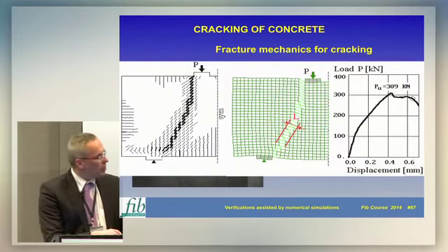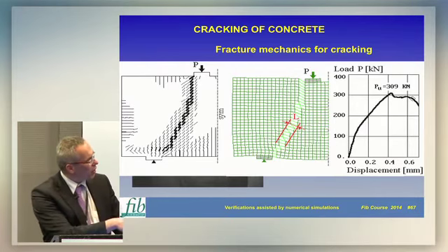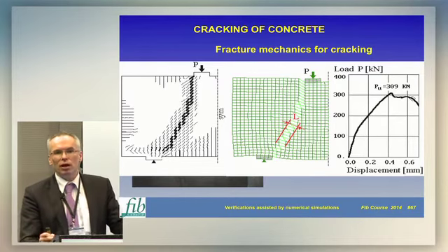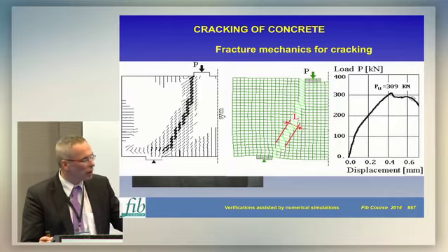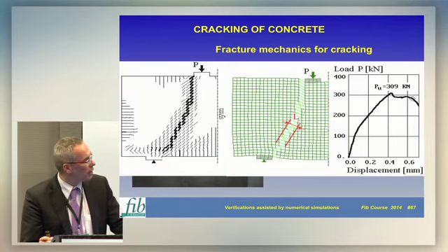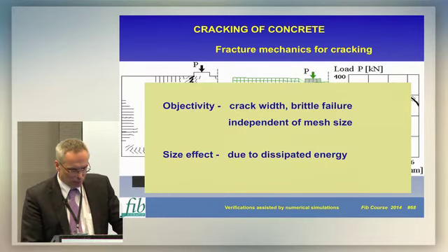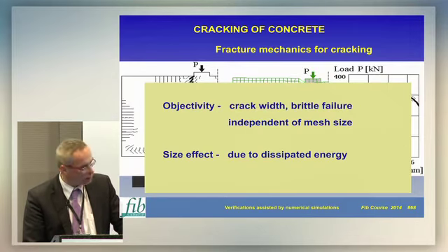What this equation finally means is that when we have localization of a crack, it localizes into a single element, which, as I told you, in heavily reinforced structures and when using large elements may not be true, because in reality there may be more than one crack inside the finite element. But this is the assumption, and a good method to address this, as I have already mentioned, is the crack band approach.